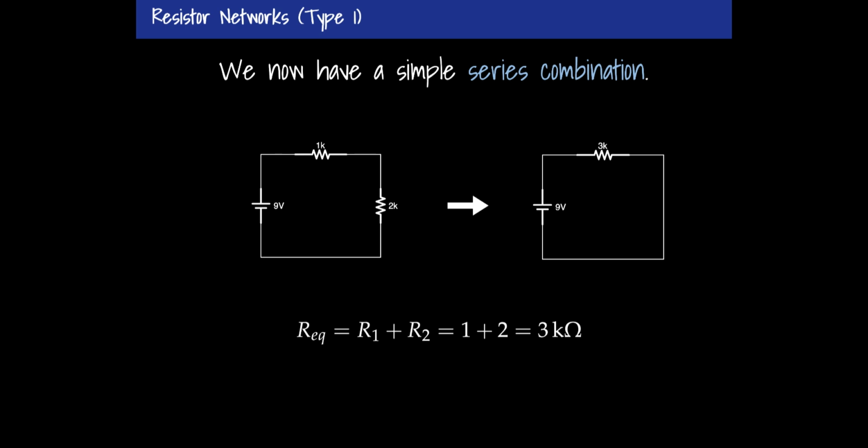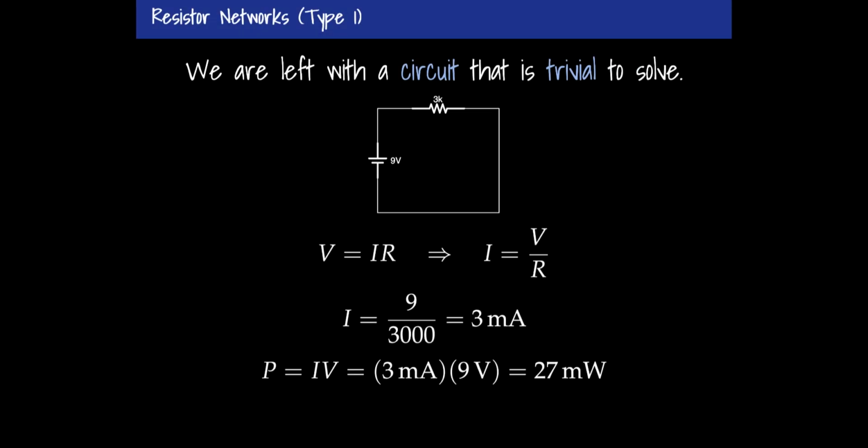I took that resistor network and boiled it down to the simplest possible circuit diagram that there is. One battery and one resistor. This is a circuit for which Ohm's law works. I can use Ohm's law to figure out what the current will be coming out of the 9 volt battery. And so, of course, that's my very next step.